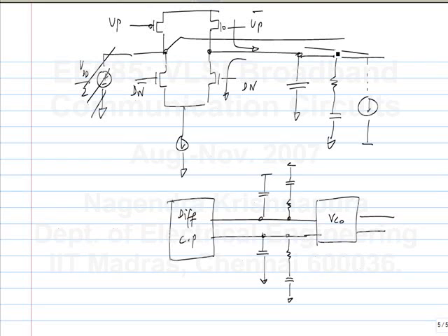So if this voltage drifts, the frequency of the VCO will slowly change. That means the phase shift between the reference and the divider will also slowly change. So that will not let this charge pump output be zero. That will give you a non-zero charge pump output which will restore the voltage. Okay.